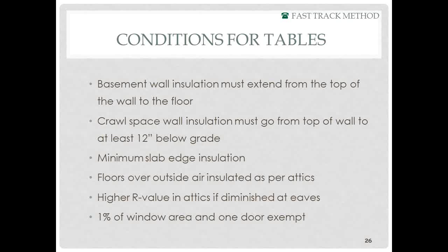There's also a detail around attic eaves. As many of you are aware, that edge of the building where the roof slope comes down close to the top of the exterior wall is a problem to get full R value there because you typically don't have the height. Builders need to pay attention to that, and they either need to get full R value all the way out over that exterior wall, or they have to insulate the rest of the attic more heavily to make up for the fact that they don't have full R value all the way out over the walls.